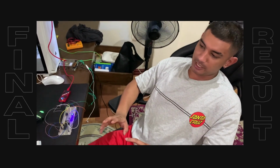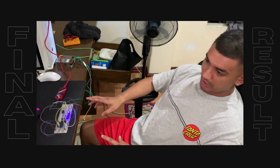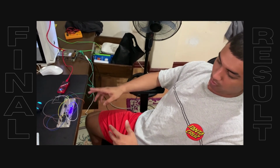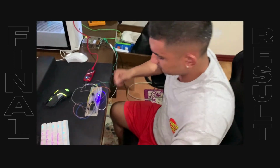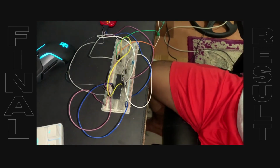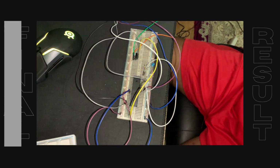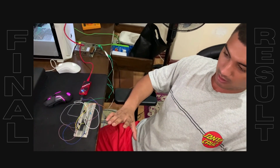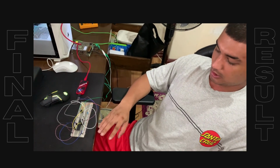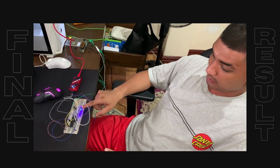For the third part of experiment 3, using delay and interrupt, we have now achieved blinking LED with 250 milliseconds interval. Now we will modify the code and make it a delay interrupt with 2 second interval. This is the last part of experiment 3. We have now achieved delay interrupt for a 2 second delay for the LED light.